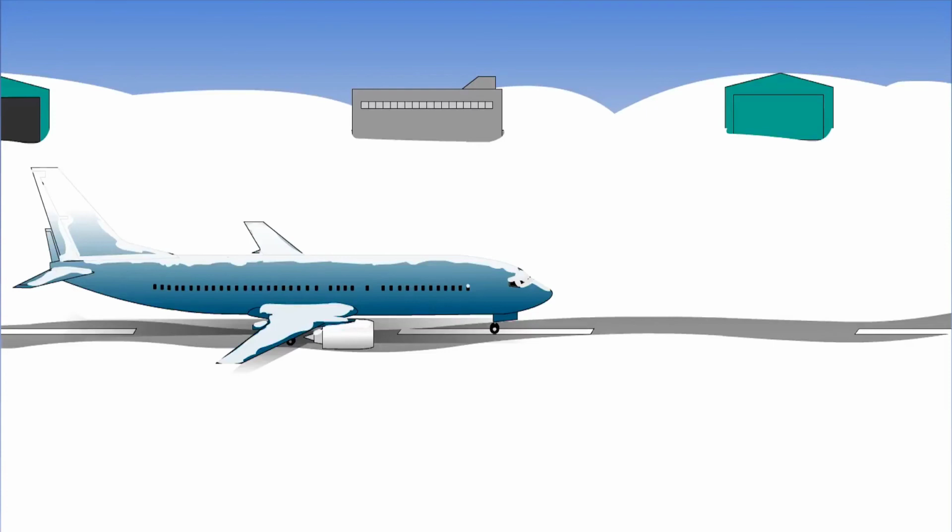If there is any snow on the aircraft, it must be removed before flight. The idea that snow will blow off the wings during taxi or takeoff is a complete misconception, as has been tragically proved on occasions. Notably, the crash of a Boeing 737 into the Potomac River, Washington, in January 1982, which killed 78 people, and in which snow on the wings and tailplane was one of several contributory factors.